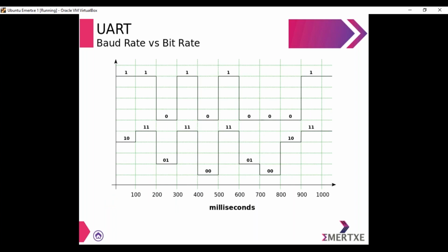So first one is nothing but in 1 second, in one time, there is only one bit being transmitted. In this case baud rate and bit rate are the same. So in 1 second there is only one bit being transmitted, so one symbol is made up of only one bit. So in the first case baud rate and bit rate are the same.